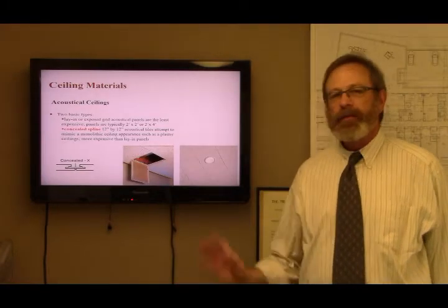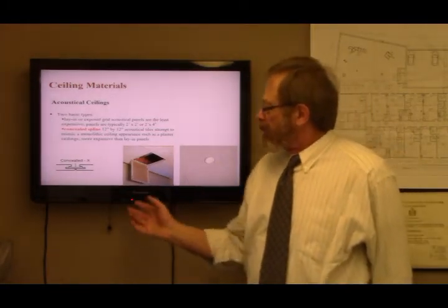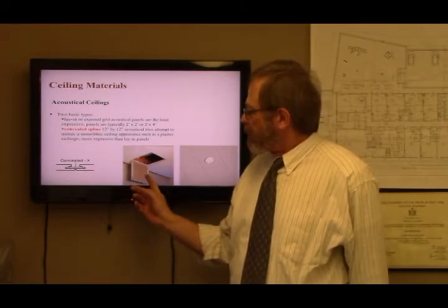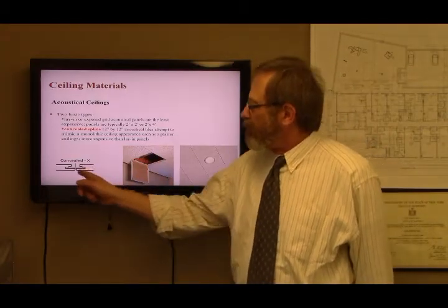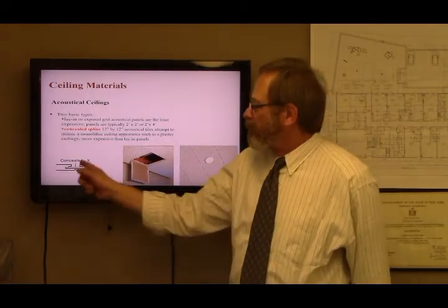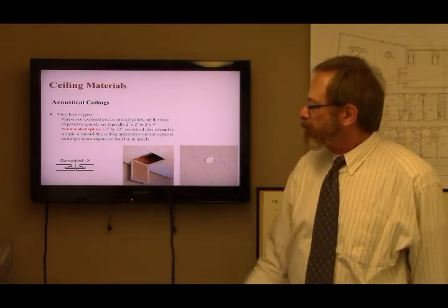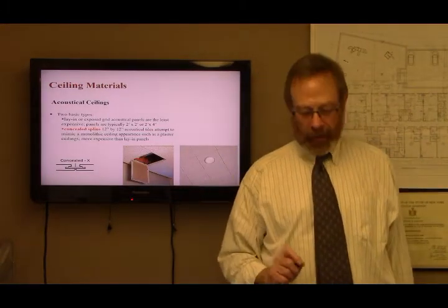So this approach is not used that often. It's very difficult to achieve. And imagine if you needed to get up into that plenum, you probably would want an access panel, because you could never do that once it's installed. You could never undo that and then redo it successfully. So with that type of concealed grid, you would want to inset your own ceiling access panel.